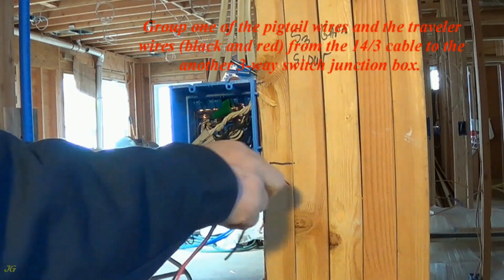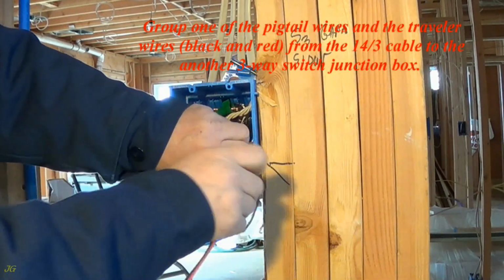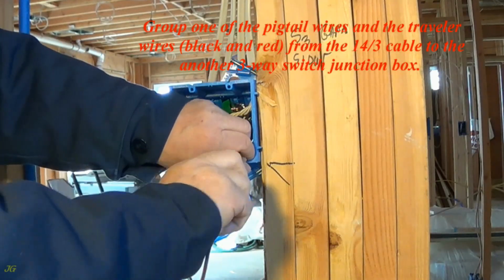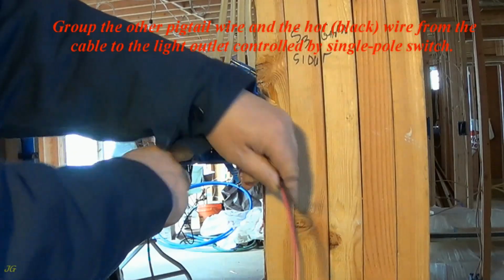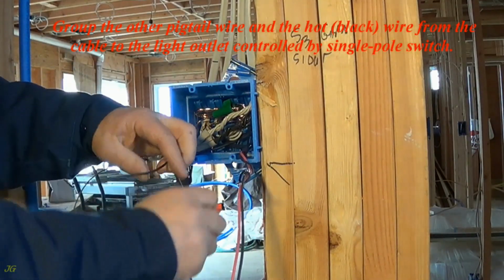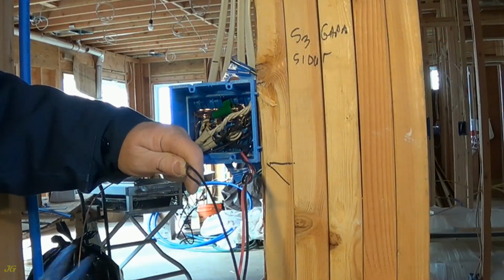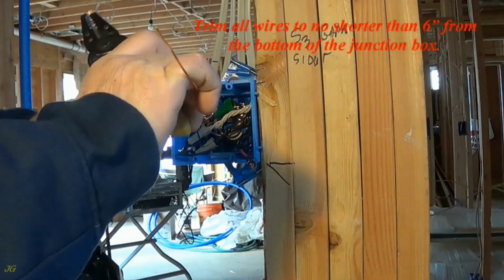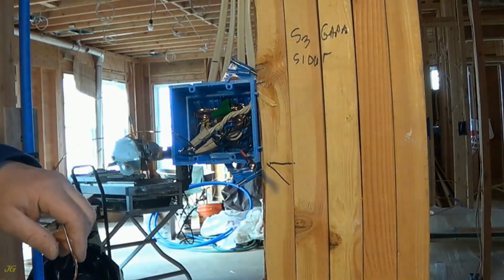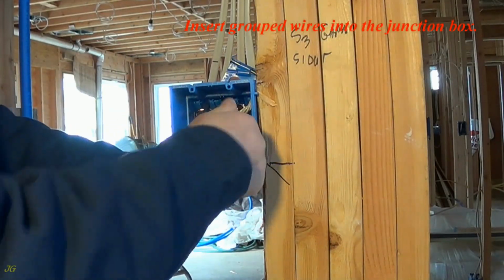Group 1 of the pigtail wires and the traveler wires, black and red, from the 14.3 cable to the another 3-way switch junction box. Group the other pigtail wire and the hot, black, wire from the cable to the light outlet controlled by single pole switch. Trim all wires to no shorter than 6 inches from the bottom of the junction box. Insert grouped wires into the junction box.